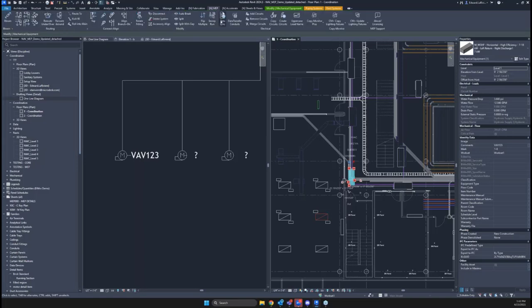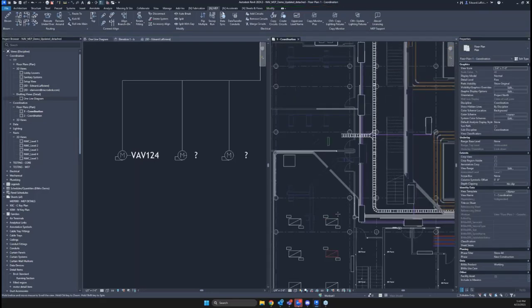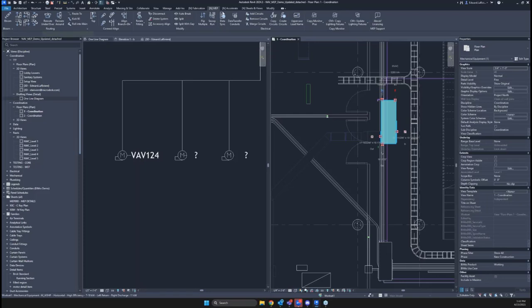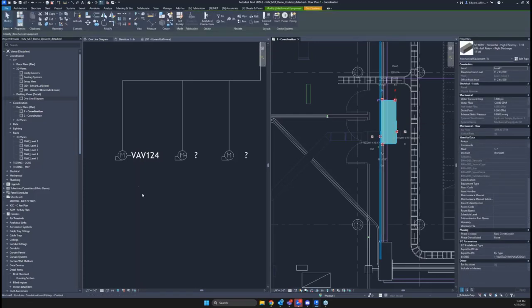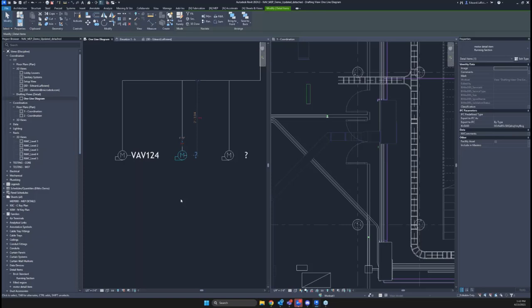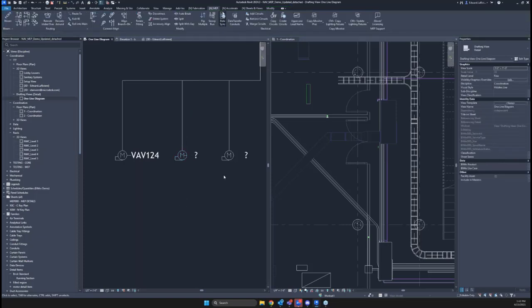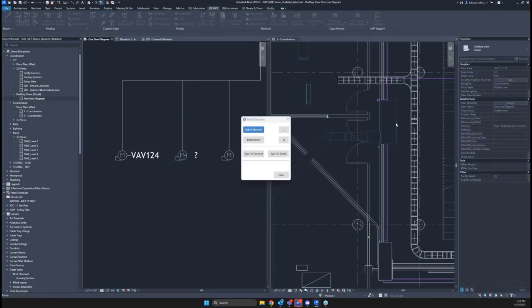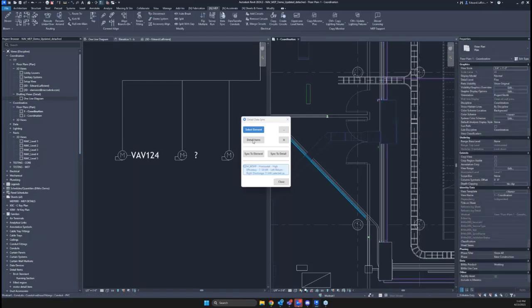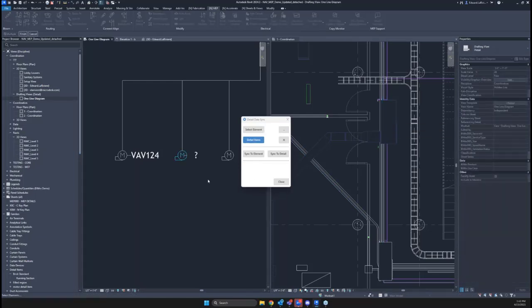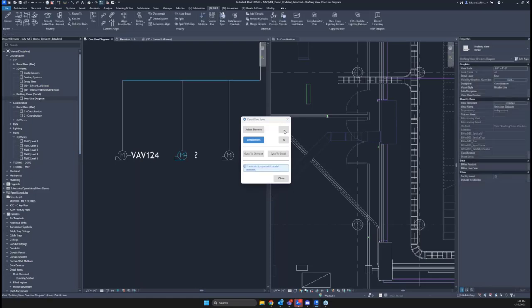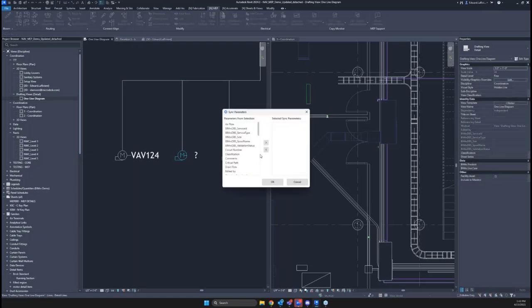Enter data sync. What's it going to do for me? Well, pay attention over here. It's going to allow us to live update data. What we're able to do is choose Revit elements and link them against detail items. So data sync says, choose a Revit element, choose a detail item, and then choose some parameters you care about.